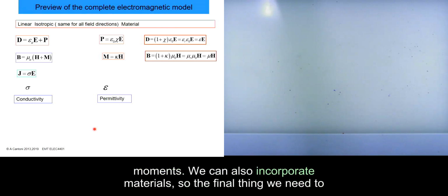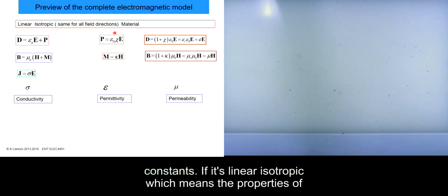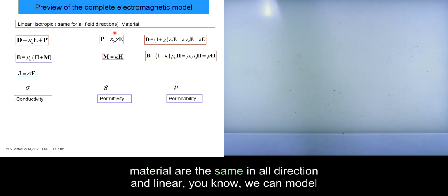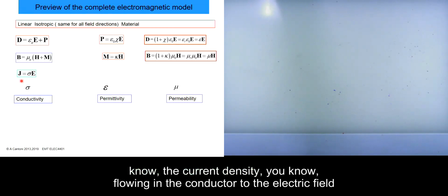We can also incorporate materials. So the final thing we need to incorporate into the model is materials, and we do that through these constants. If it's linear isotropic, which means the properties of the material are the same in all directions, then we can model a conductor by the conductivity. And conductivity relates the current density flowing in the conductor to the electric field strength, right?